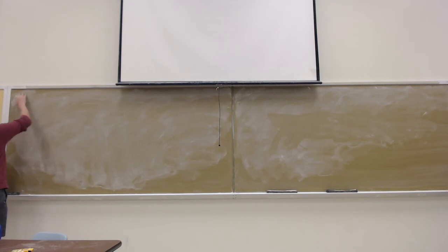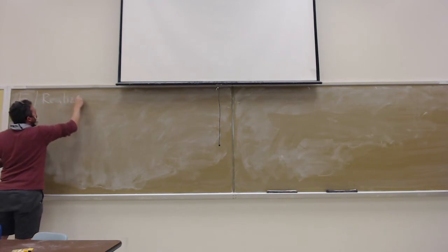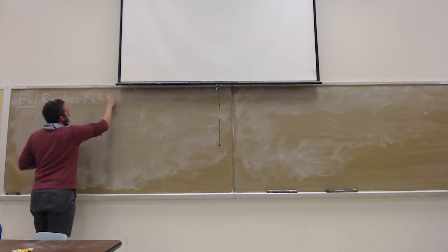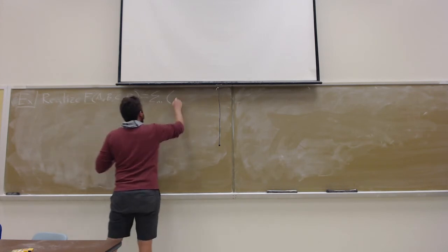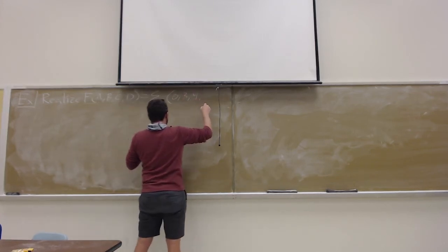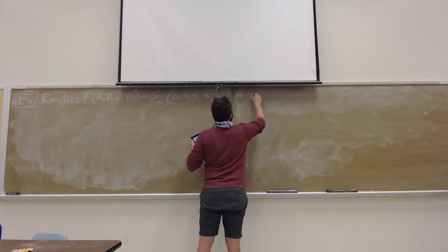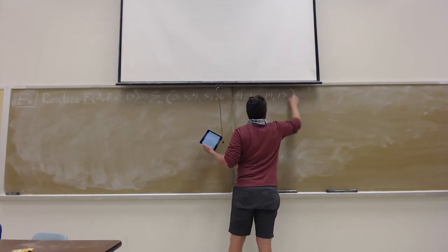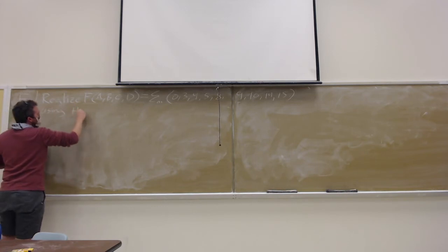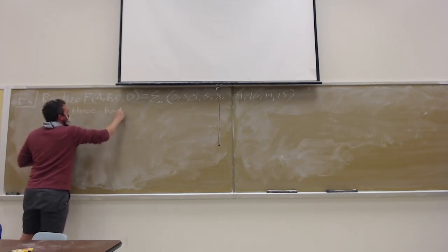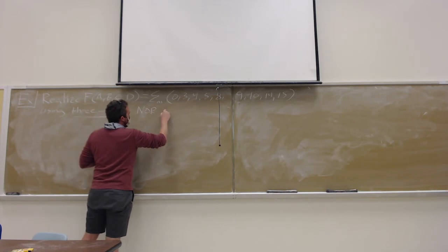So remember, we're trying to realize this function f, which is a Boolean function of 4 variables, equal to the sum of minterms 0, 3, 4, 5, 8, 9, 10, 14, and 15, using three-input NOR gates. Three-input is our fan-in constraint, and NOR gates is a technology constraint.